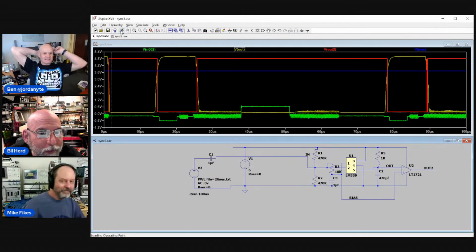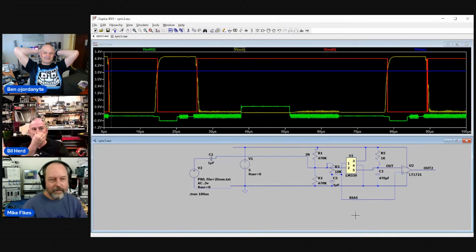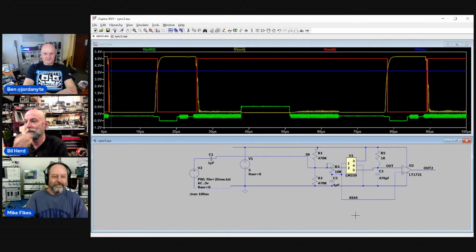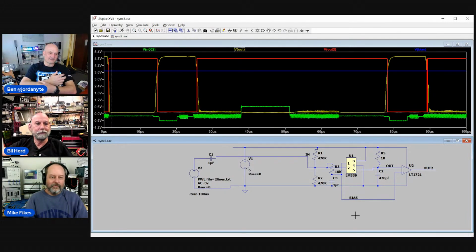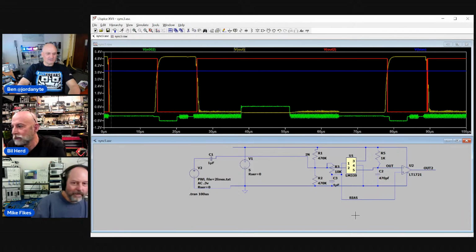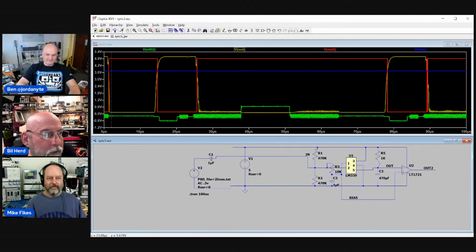This is what Spice really did for electronics designers, though. It made the design process way more experimental and less scientific. Yeah. I still think the most efficient way to design is honestly to calculate what time constants you want. For a circuit like this, you actually do the math, because it's not difficult. It's really not hard. You're not doing calculus. It's just simple formulas. So work it out and say, well, this should be about right. Then you simulate it to verify that you haven't made a silly mistake. Then you build it and measure it and confirm.